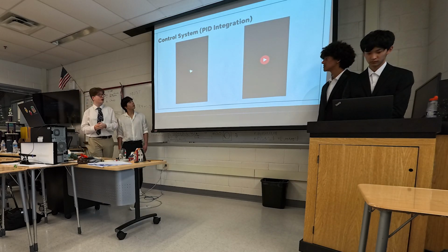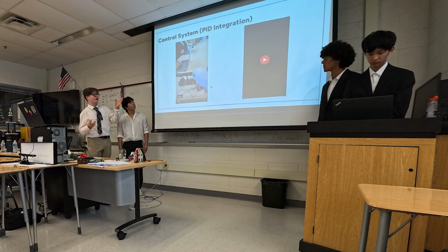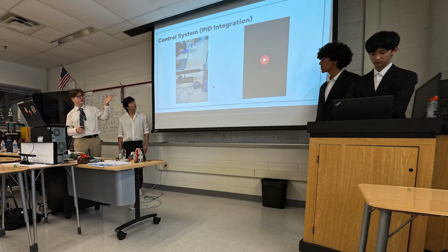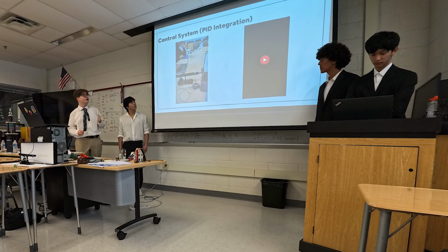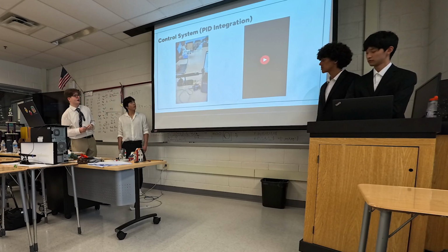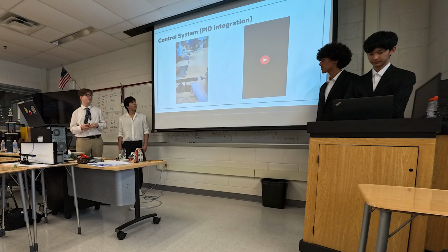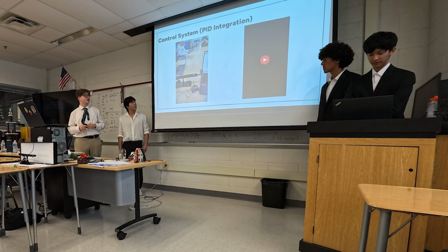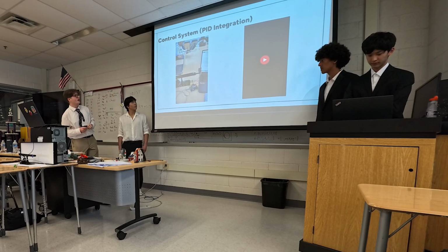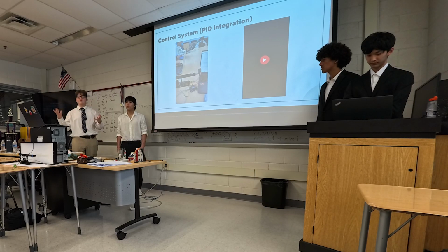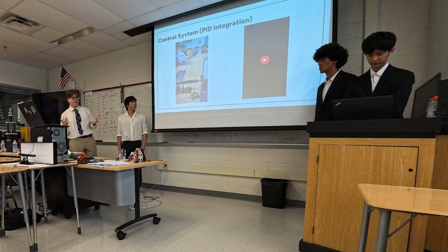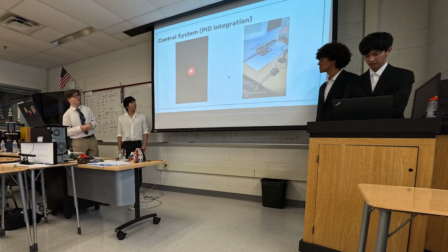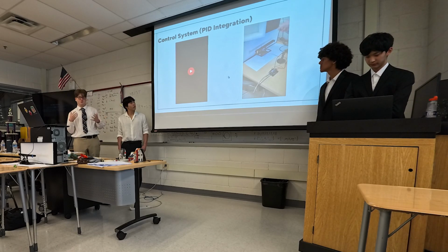So here I want to show you guys two examples of PID working with an ultrasonic sensor. And here the ultrasonic sensor also had a lot of dead spots, so it's very close to the edge of the beam. But you can see that it did balance it, and then you can nudge it. Eventually it'll balance it. Also notice that the ball is banging into the edge of the beam a lot, and this was a problem because that just made it easier for the beam to balance the ball. And now we're going to show the computer vision approach, which I think is much better, and it doesn't really tend to touch the beam as much.